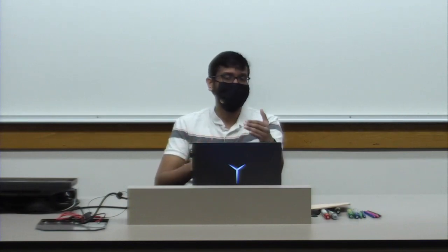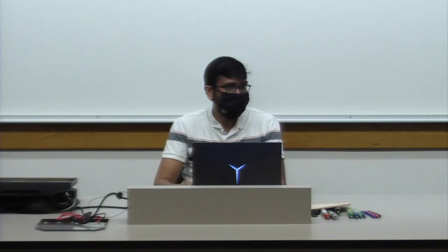One thing I've talked a lot about is how we take a piece of code and translate it to hardware. A test bench does not need to care about that, because in reality, you're never going to implement a test bench. So you can write it in as abstract a way as you want. They have something called a program block, which is essentially a sequential block where you can write code line by line, and it will operate one line at a time. So you can write a test bench in as C, C++, or Python-like a manner as you like, and it will mostly accept everything as long as it's legal SystemVerilog syntax.